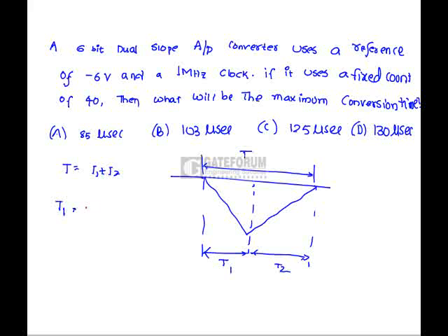Here T1 depends upon the time to count, that is 40 divided by 1 into 10 power 6, that is 40 microseconds.